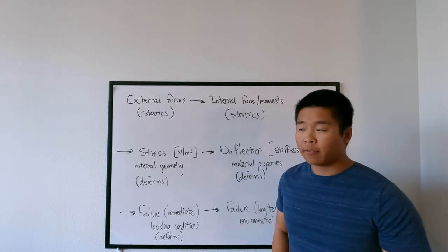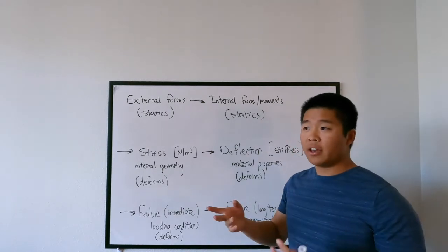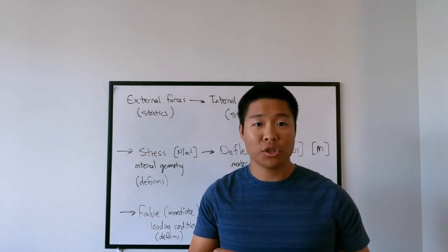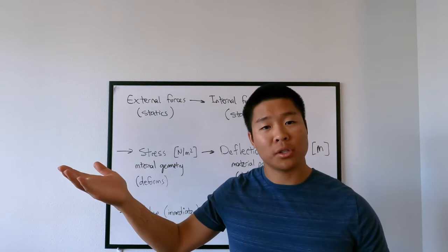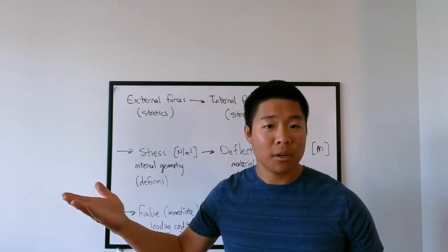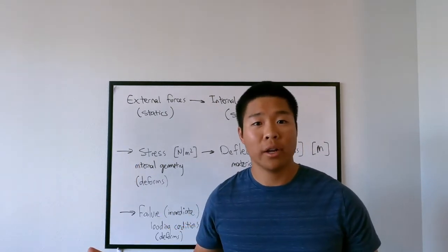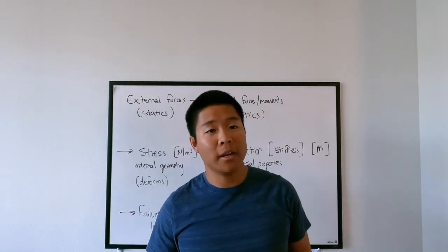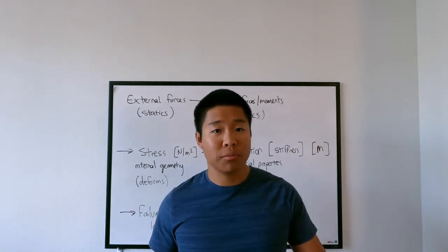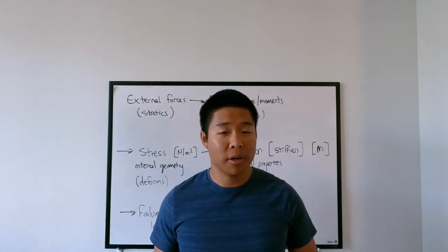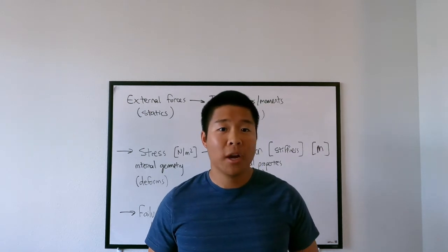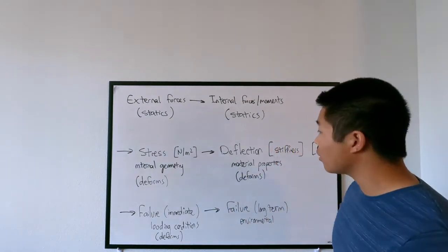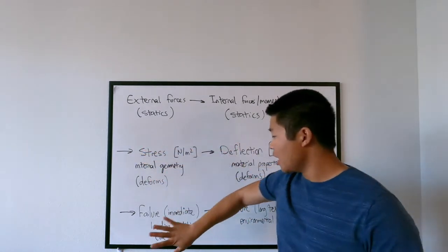And lastly, we have, of course, temperature effects. Like I mentioned, if something is super hot, it doesn't necessarily have to be a cyclical temperature effect. As you probably already know from chemistry, steel gets a lot softer when it's super hot. So if you have a pipe that has a pressure rating, and the fluid flowing through it is extremely hot, then the pressure rating actually goes down. So you need to use a stronger pipe as the fluid gets hotter, okay?